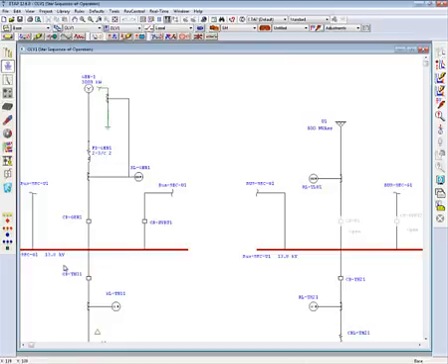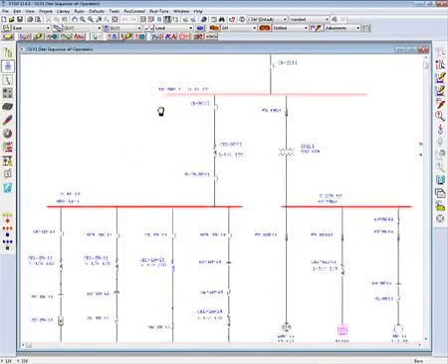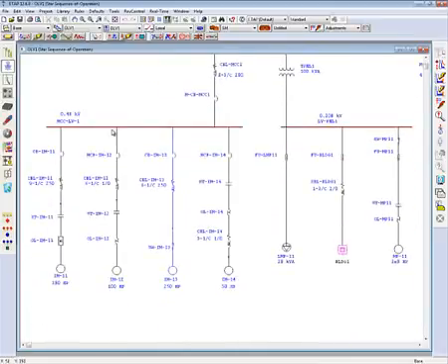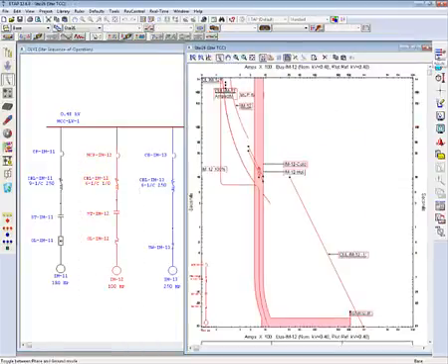So what we are going to do is try to set up one protection scheme. We are going to see how we can protect our motors. Let's for example take motor IM12. If I select the motor, rubber band all of the equipment protecting this motor and create a star view, I can see the time current curve, or star view, of the protective devices and the element which needs to